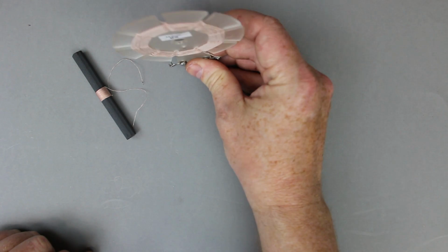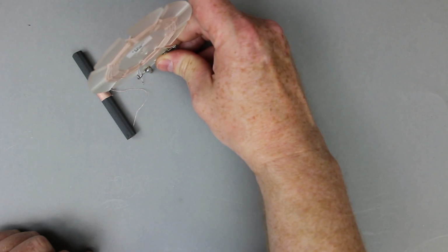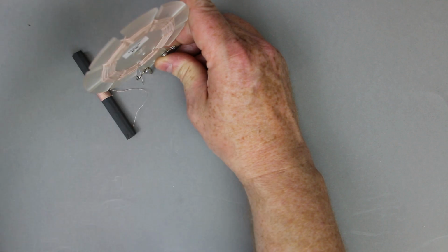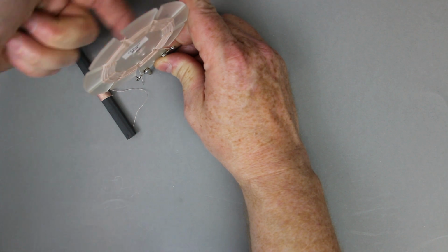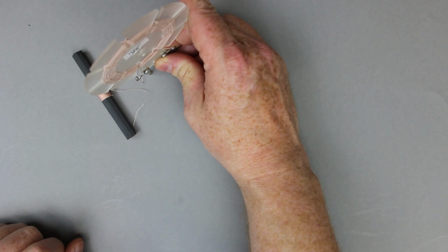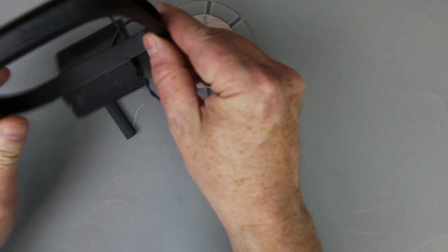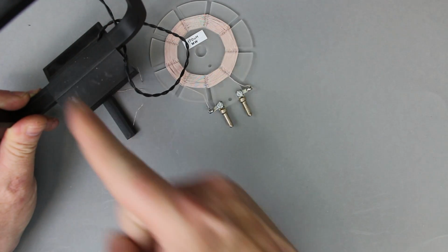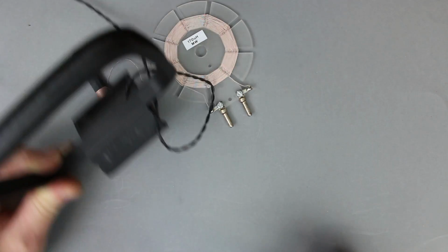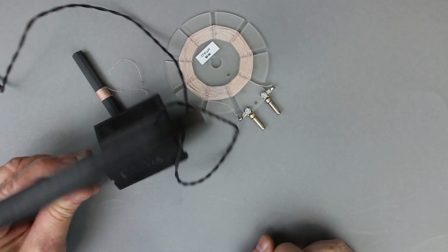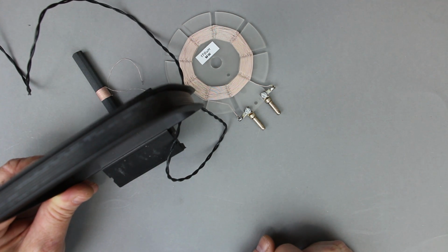And with this antenna, which is usually used upright, you can do the same, and you see you have to place the axis of the spiral coil in the direction of the interfering transmitter. And the same is true, of course, with this one. You also have the coil, and the axis of the coil is the direction where you place your magnetic antenna to blank out interfering stations.